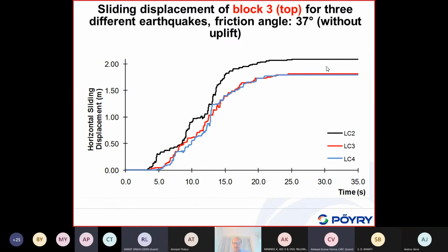Some are similar, but one deviates a lot. In a nonlinear analysis, if you do an assessment of the safety with only 3 analyses, you have to take a maximum. But according to some codes, if you would do, for example, 11 analyses, you could use mean or mean plus 1 sigma response values rather than the maximum. But this is for building structures, not for dams.